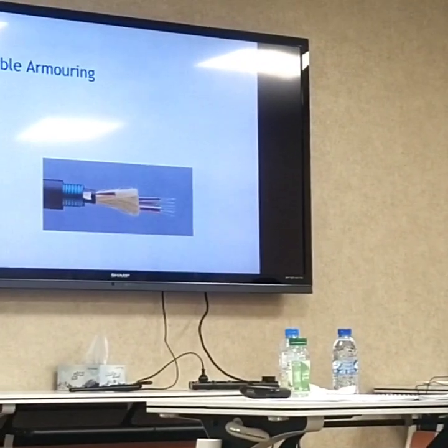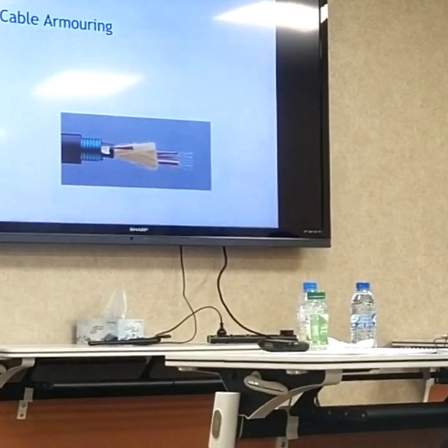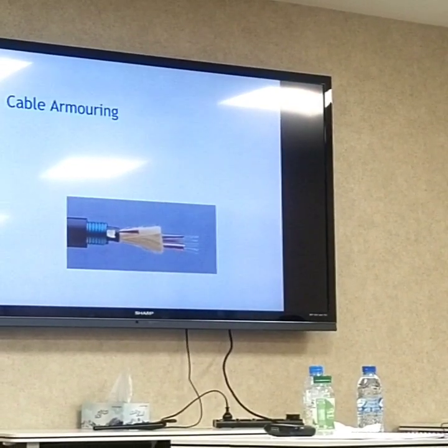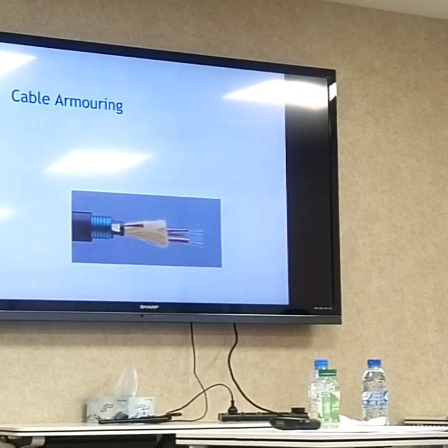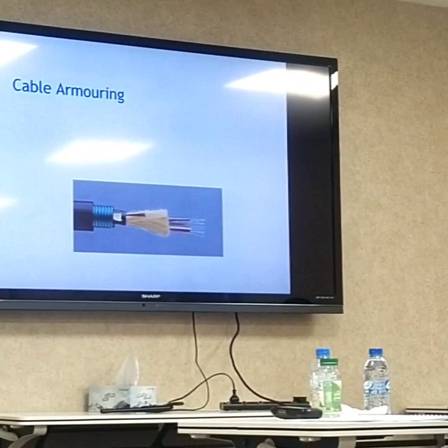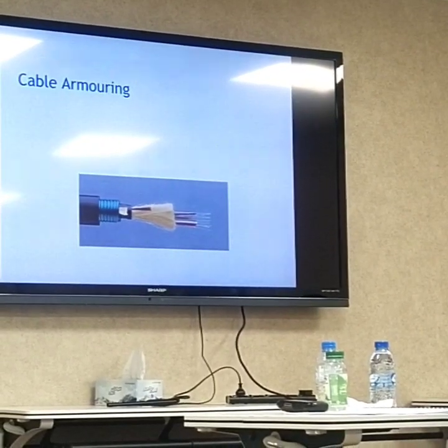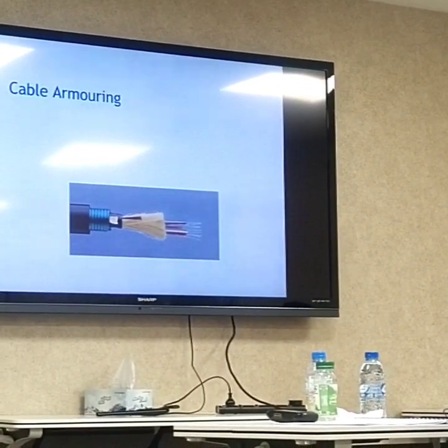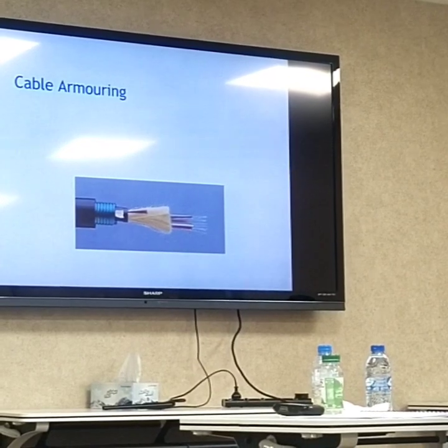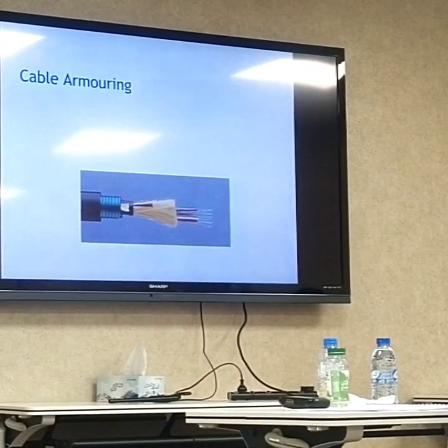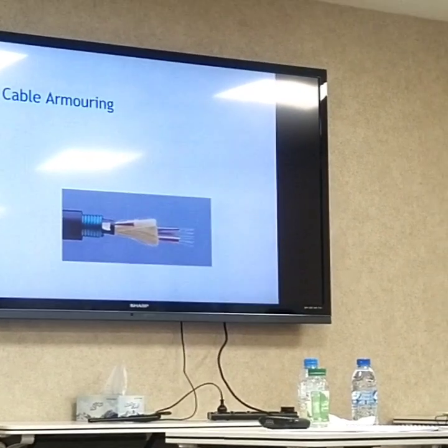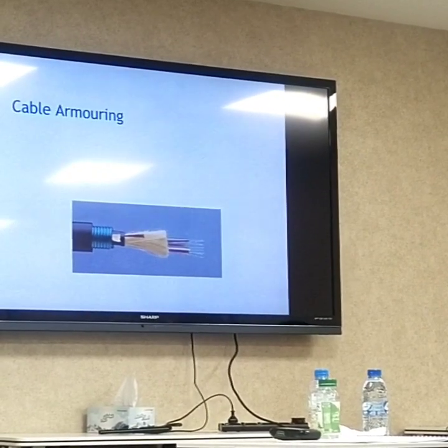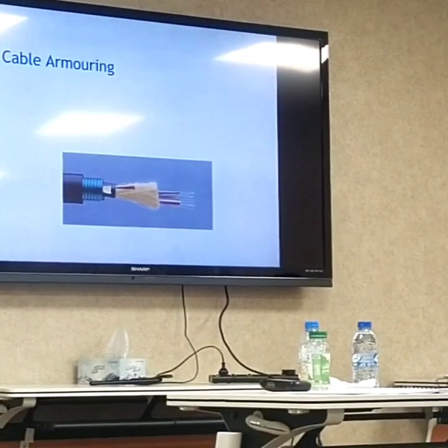Then the cable armor. As I said, it is not a must for all cables to be armed. It depends on the application and the expected conditions. If we are expecting the cable to run within an area where external mechanical stress is unlikely, it is better to be non-armed. Less cost, less weight, easier to lay and handle. But what if we are expecting the cable to be exposed to some external forces or stresses?